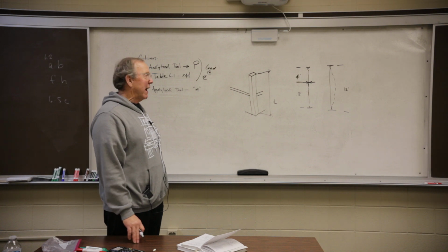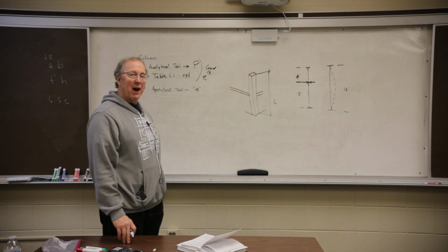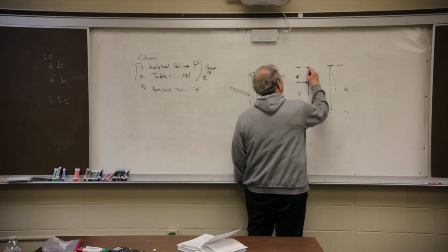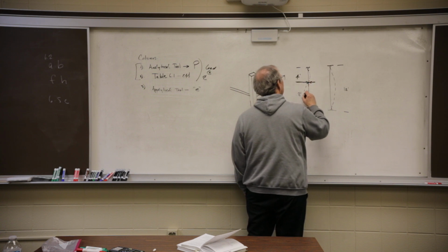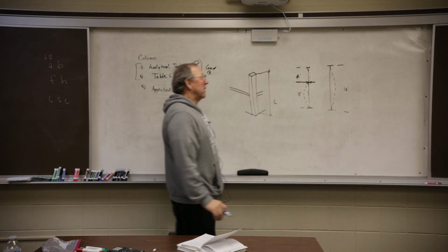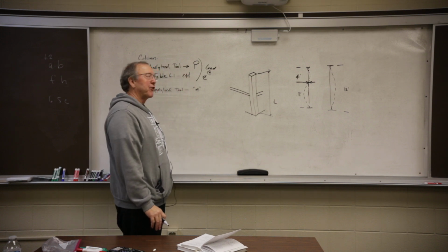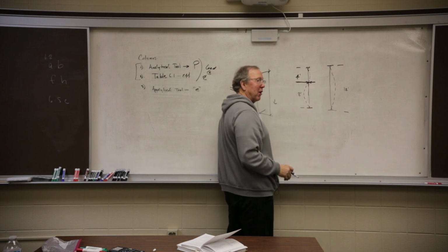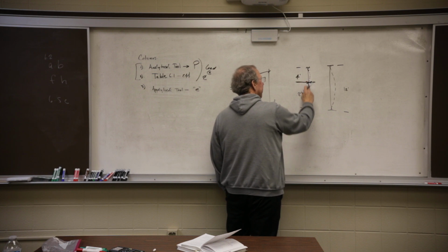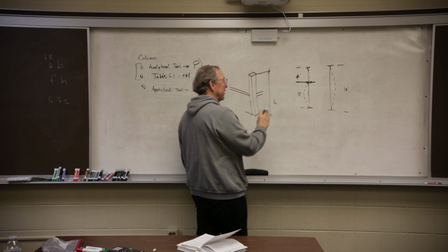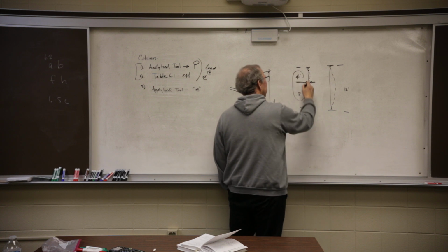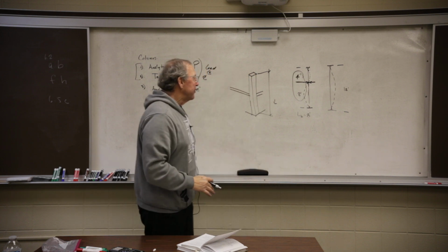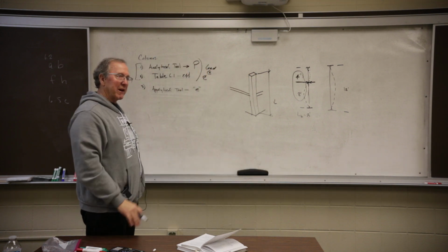If that's the case, now I've got a brace at 4 foot from the top, 8 foot from the bottom. If this buckles, it's going to buckle like this. Hopefully you can see when I push down, the first buckle is going to be this one down below. It's going to take a lot more load to buckle a short member than a long member. So in this one, the unbraced length of the member is going to be 8 feet. It's the largest unsupported or unbraced section.